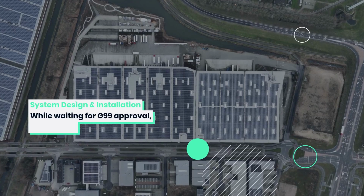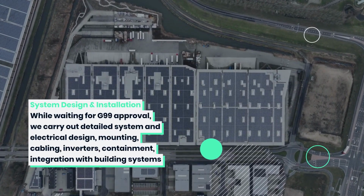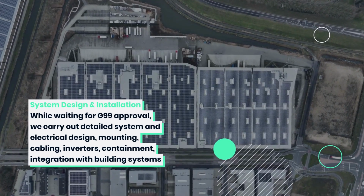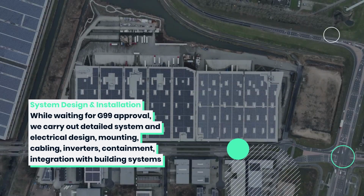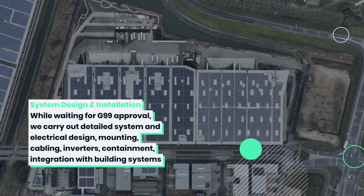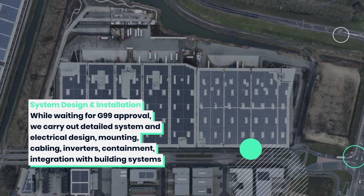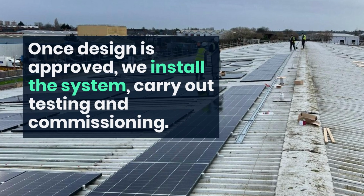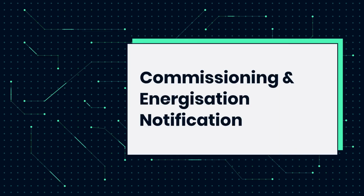System design and installation. While waiting for G99 approval, we carry out detailed system and electrical design, mounting, cabling, inverters, containment, integration with building systems, lightning protection, fire safety, etc. Quality assured under MCS MS 3002 and BS 7671 standards. Once design is approved, we install the system, carry out testing and commissioning and energization, notification.